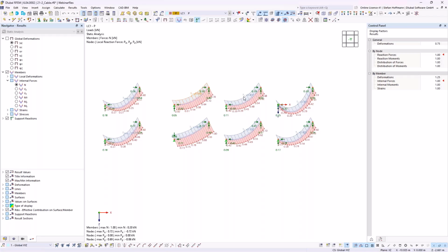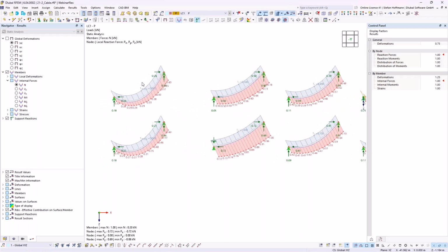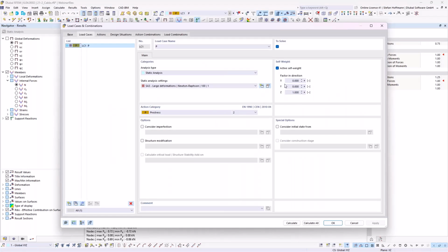We can have it less. This is also stable. This is also stable. And if I would lower it even more, then my structure will become numerically unstable or nonsense inner forces will arrive. And then this is what this function is doing internally. So it's a minimum force definition to reach a certain convergence or equilibrium. So of course, the dead load is activated for both models.